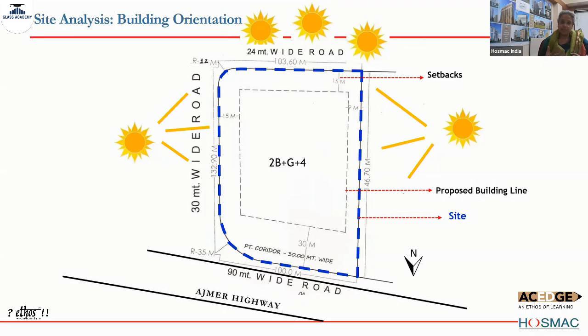So when you see the PPT in front of you, on the screen, we are going to analyze the movement of the sun and the placement of the building, because when we understand that, we are able to locate the longer length of the building towards the north side. Then there is less penetration of direct sunlight, and that should be our aim, if possible. So the form can be decided with respect to the climatic conditions.